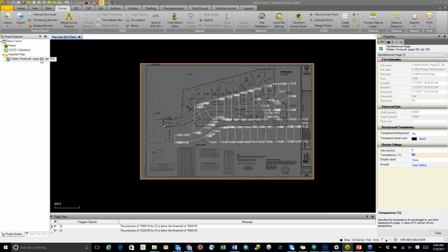So real quick, another thing which I didn't show, I had it ready, but if you bring in your field data and you want to start drawing lines off of your points from the field, you can easily do that. In the Create COGO, there's an option to select points, or you can either type the point names in, or you can just select a point from the map and then draw from point to point if that's what you wish.